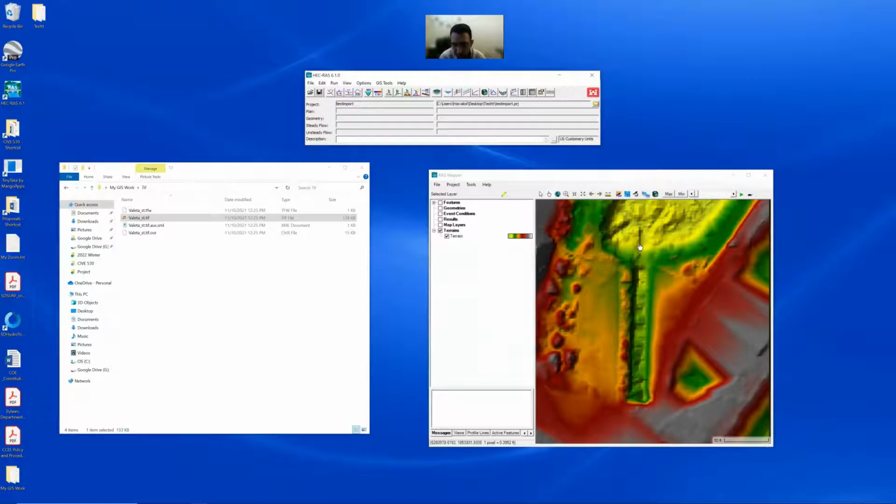You need to have a river line and you need to have some notation for the bank station, the boundary of the bank station, and overbanking, things like that. So basically, when you go to geometries and you add a new geometry here, call it whatever you want, geometry 1, 2, 3. And then it gives you a list of items so you can create. So your river line, most important thing.